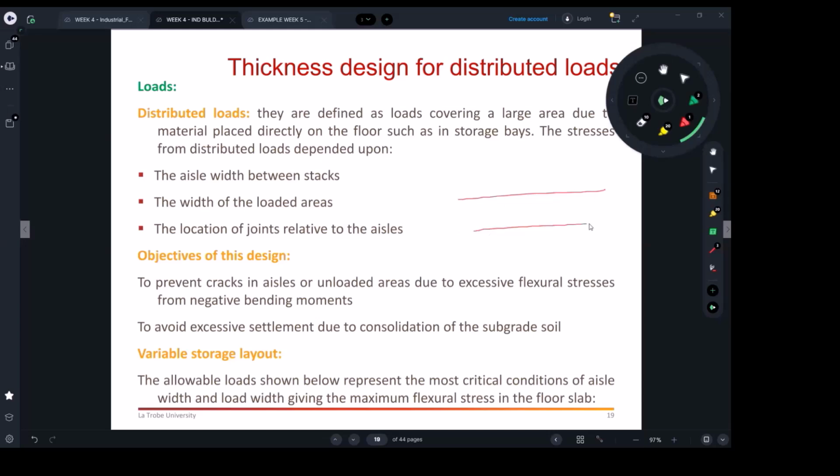When I was showing you, this was your slab, that's the soil, this is the post. There is a 45-degree angle of repose. If I have another green post, bigger, wider, your angle of repose will be what? Bigger as well. This is for the green. I'm just looking at a side view, and this is for the red.